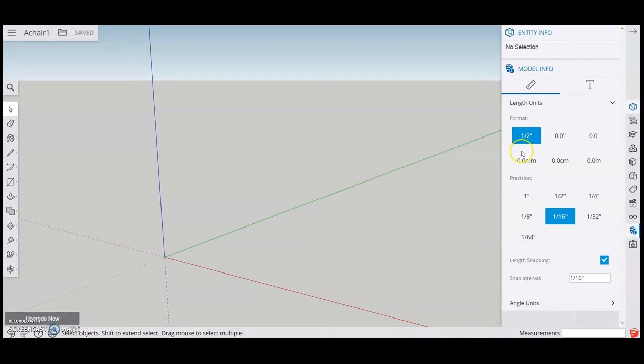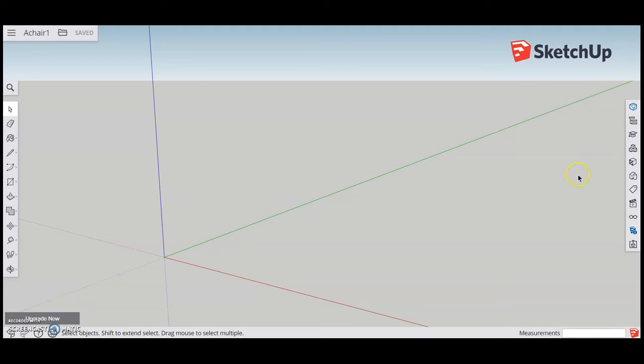So you'll see our standard measure right now is set to about a 1/2 inch standard of measure. We're looking to use centimeters for this one because I think it'll keep everything simple and hopefully help you to understand a little better about what we're doing and the measurements and how they relate to each other. So I'm going to have you select 0.0 centimeters for this one. And at any time you can hit this arrow at the top that will close this panel to reveal more of your modeling window.